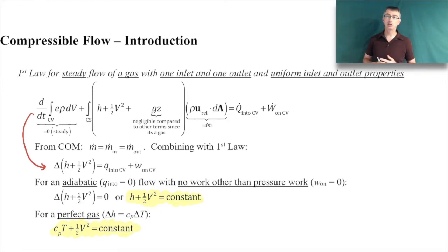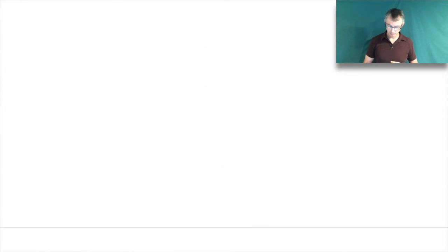That if you make a perturbation somewhere in the flow, it's immediately felt everywhere instantaneously for a truly incompressible flow. But when the flow has some compressibility to it, it takes time for that disturbance to propagate. So if you make a change somewhere, it takes time for that disturbance to be felt elsewhere. And you can start to run into some really interesting situations where you start to move as fast as the disturbance propagates. So basically, you start to move as fast as the speed of sound, or maybe even faster than the speed of sound. In those kinds of situations, you get the development of these kinds of shock waves.